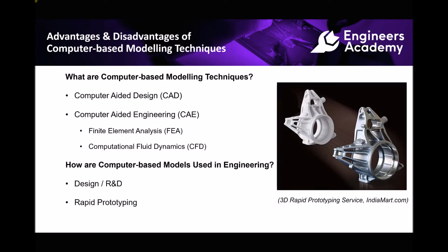Now, another huge benefit, particularly of computer-aided design, is that we can now produce rapid prototypes of components. And a rapid prototype is a physical component that's identical to the final component, except it's made out of a resin or a different material. Now, this is excellent if we want to see how two components are going to mate, or whether a new component is going to fit in with an assembly, and it saves the expensive costs of manufacture, yet we can still hold that physical component and we can actually physically see how it's going to assemble with other components without the high costs associated.